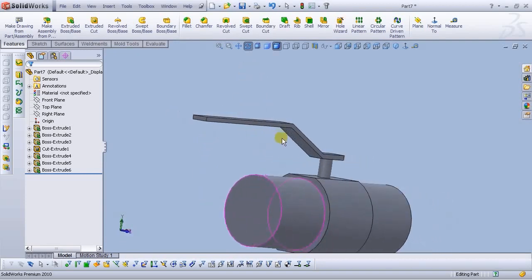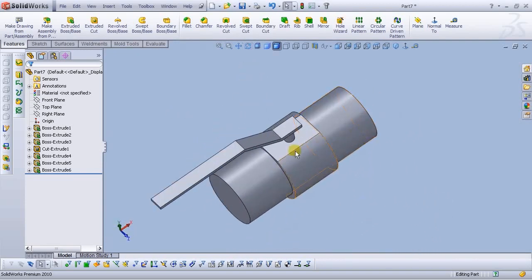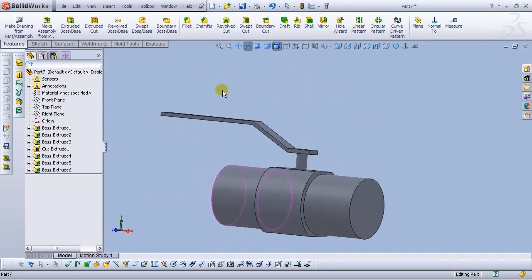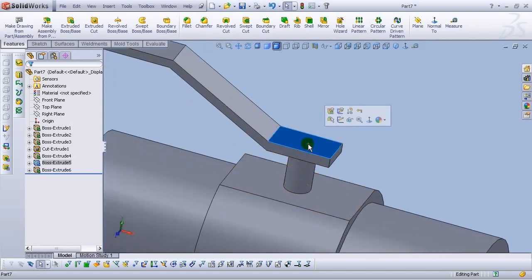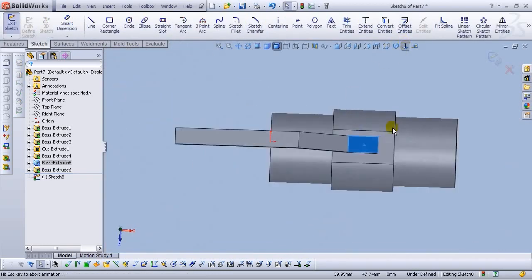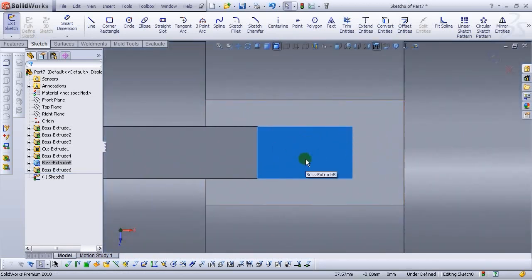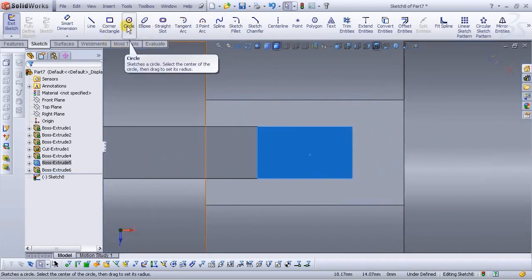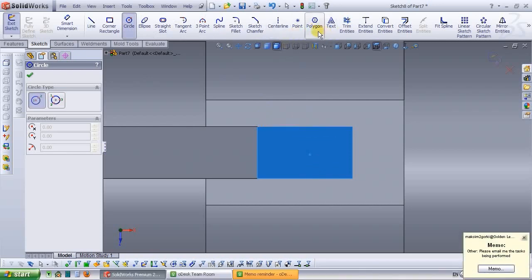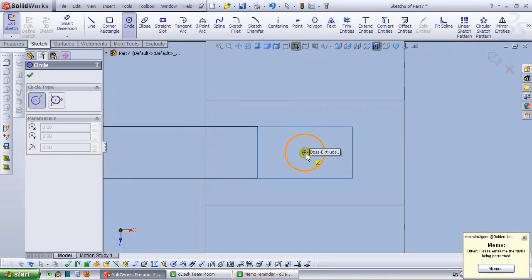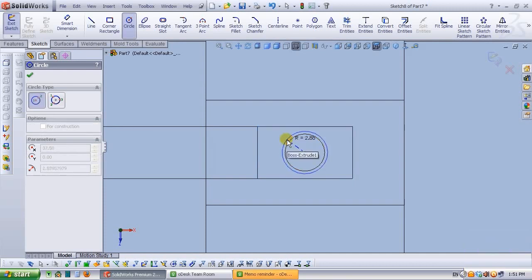Okay. And let's make it 70 millimeters. Okay. 45 here. 50. Now it looks good. Okay. Let's offset these entities by 1.8 millimeters in the reverse direction. Select OK. Let's draw a line right about here, and let's extend these entities.